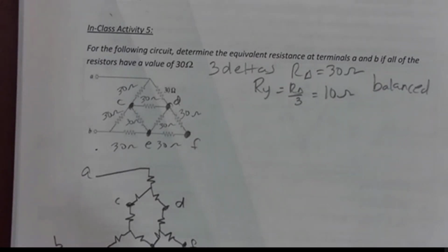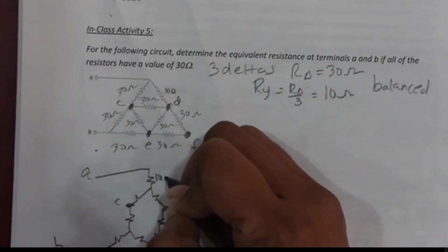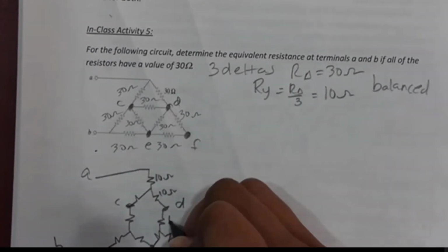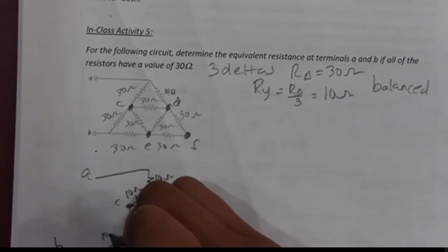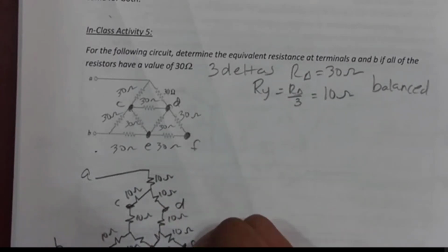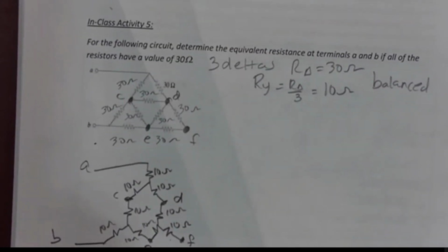Okay, so when you're looking for equivalent resistance, we have a dangling resistor. A dangling resistor is one where no current flows, so it does not impact the net resistance. Can anybody tell me where the dangling resistor is? The one at F, that's right. So when I look for the equivalent resistance, this dangling resistor has no effect on that answer. Because it's not in the loop and it wouldn't have current flowing through it if I put an ohmmeter across it, this resistor is now gone from the calculation. It's called a dangling resistor.